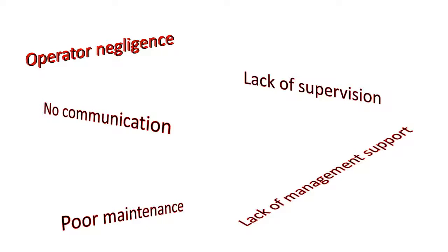Seriously though, to put these forward as root causes stops any further investigation in its tracks, and it seems that nothing can be done to address future failures. And that's when we become disillusioned with root cause analysis. So what should we be looking for? We should be investigating 3 levels of cause if we want to eliminate failures.